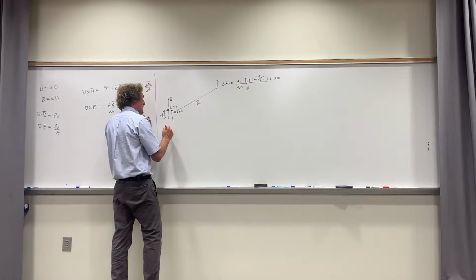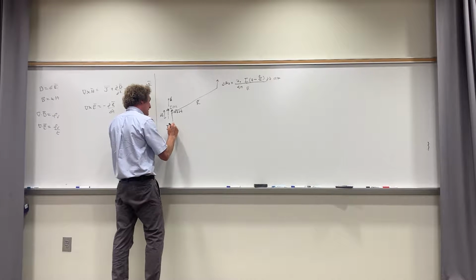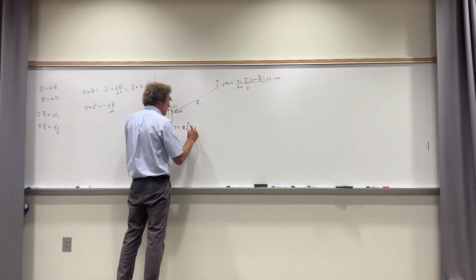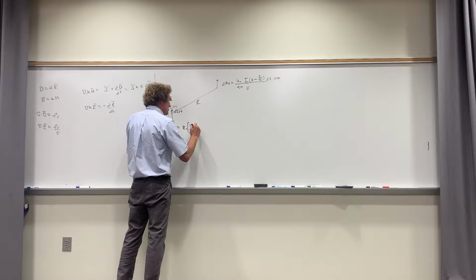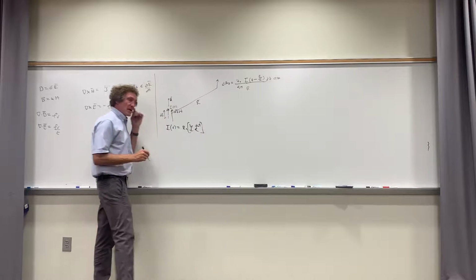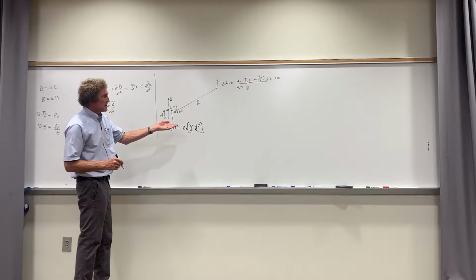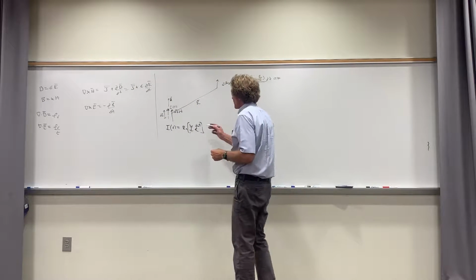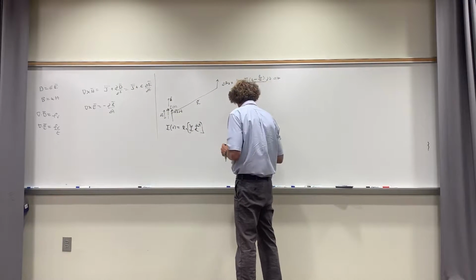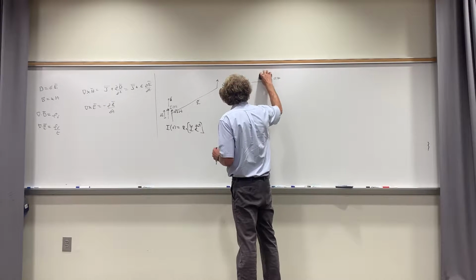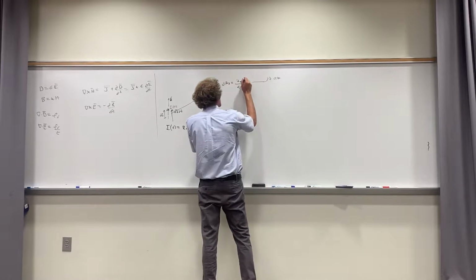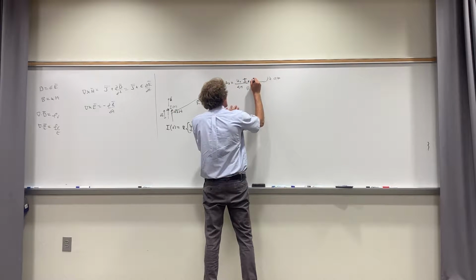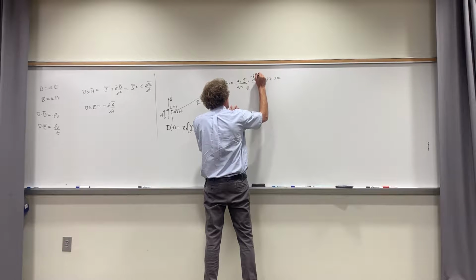And that means this I here, I of t, is really the real part of I phasor, a vector phasor, times e to the j omega t. Because I've got e to the j omega t here, when I put e to the j omega t here and take the real part, what this breaks down to, I should do this one time, but I'm going to leave it like this for now, is simply I naught, whatever the value of I naught here is, e to the minus j beta r.